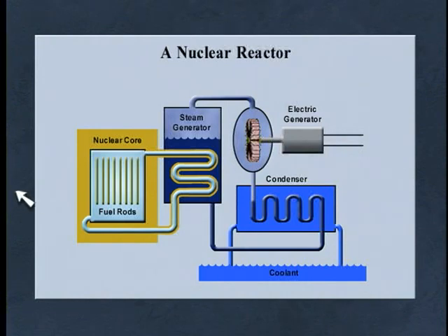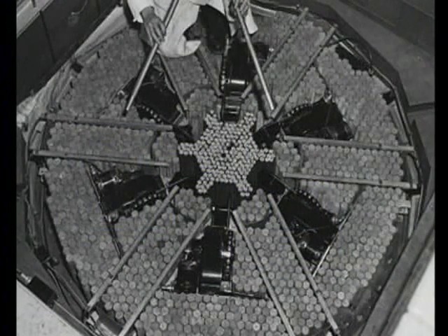In modern commercial reactors, uranium fuel, sometimes enriched in uranium-235, is shaped into long, pencil-thin rods, and these rods are encased in zirconium metal to keep the uranium and their decay products confined. A nuclear power plant may have several hundred to a few thousand individual fuel rods, and they're arranged in easily installed units of a few rods apiece. The fuel rods are arranged in a regular pattern, so they'll irradiate each other with energetic neutrons. This process leads to a sustained nuclear reaction.